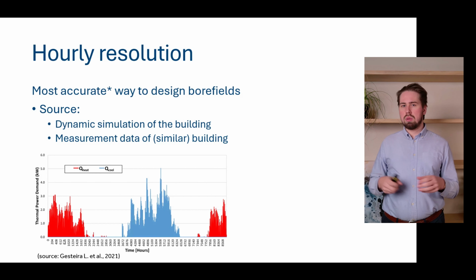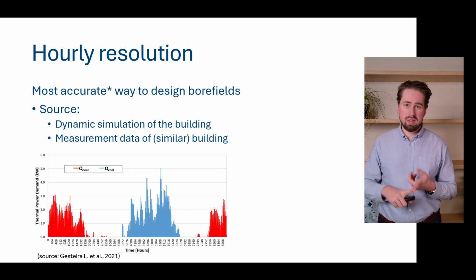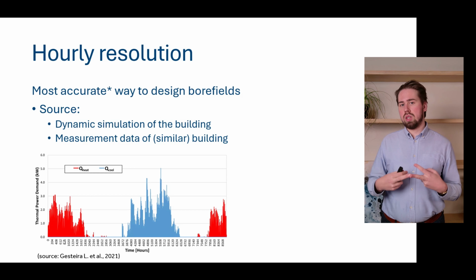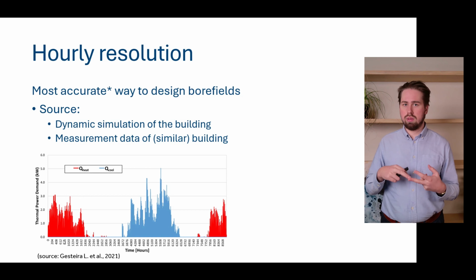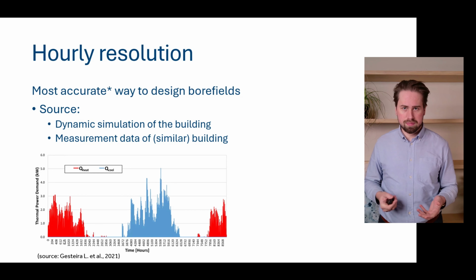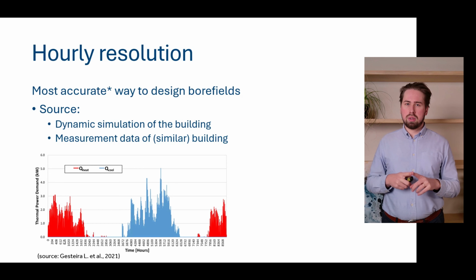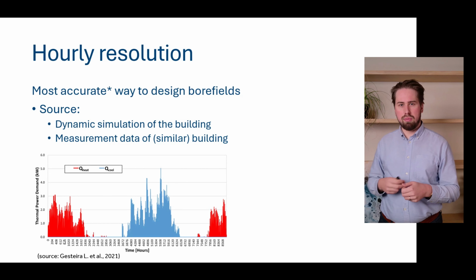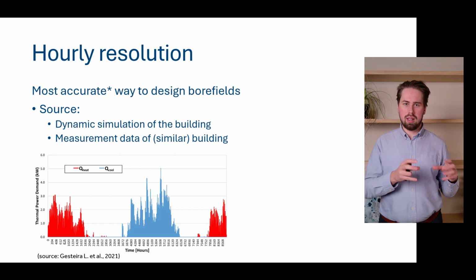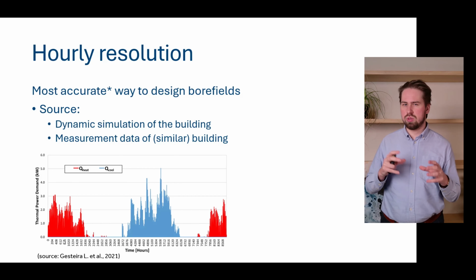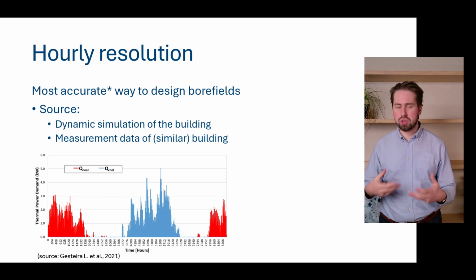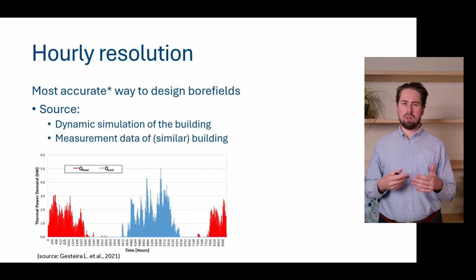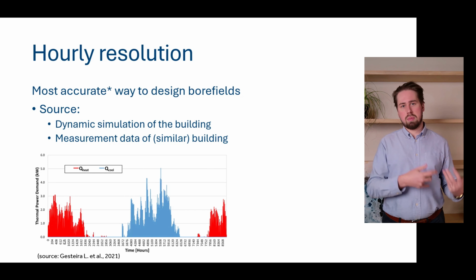Now, we can find these hourly loads based on measurement data, or we can run it through building simulation software like Vicus District or Vicus Buildings, IDIs, VABI Elements, IDSV, and so forth. What also is important is that you have already simulated the building before, that you cannot just take the profile and put it onto another building. Dynamic simulations are really, really sensitive to the building type, the control strategy, and so forth. So please make sure that whenever you extrapolate from certain profiles, that they are accurate and representative.